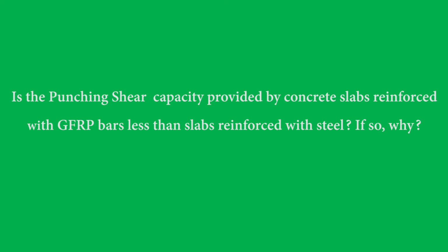But according to the research, because of this friction of aggregates, we don't need to take the k value less than 0.16. So this kind of compensates for the smaller amount of intact concrete that forms in the GFRP bars.